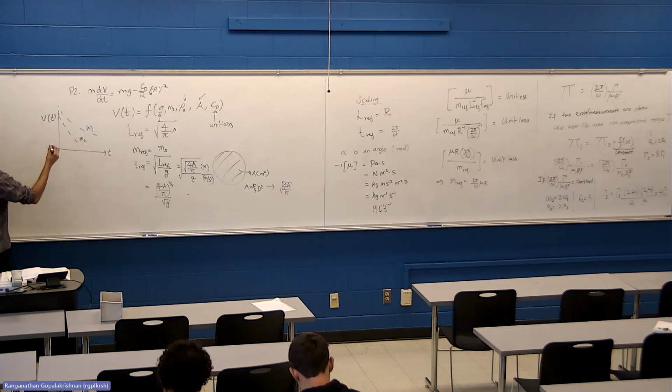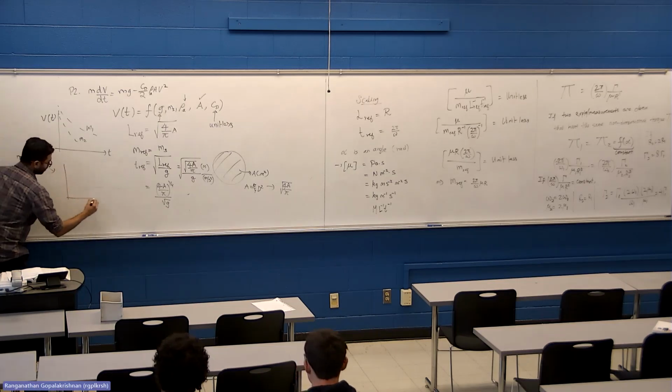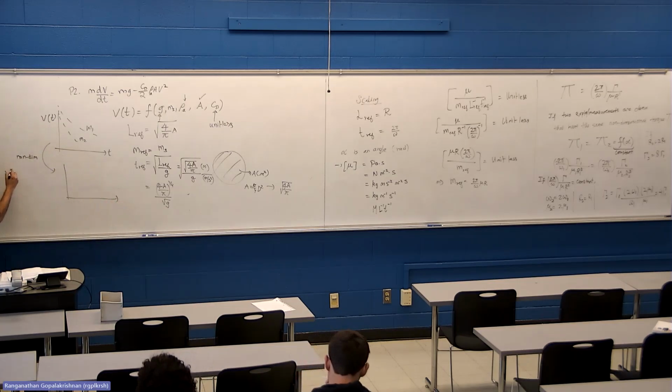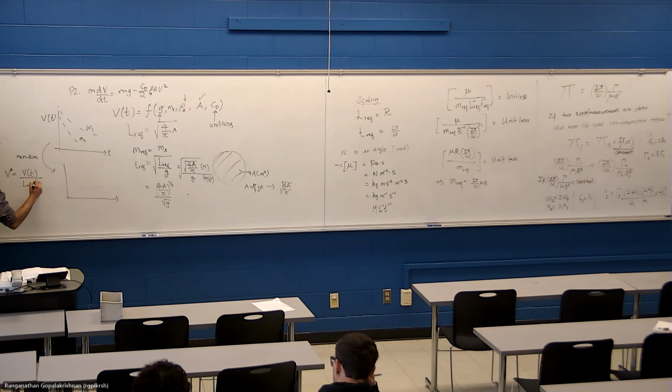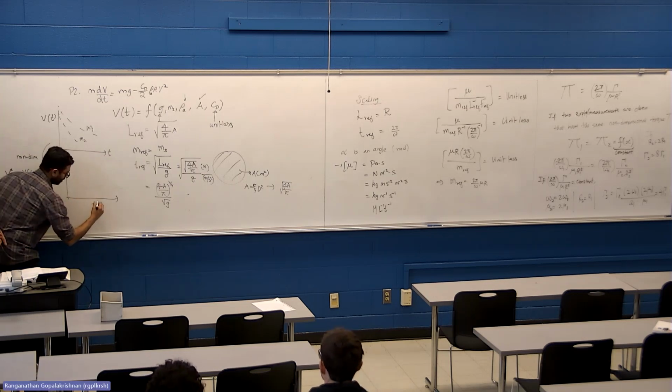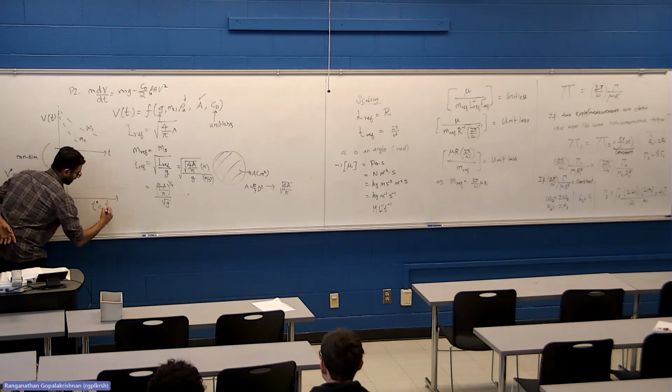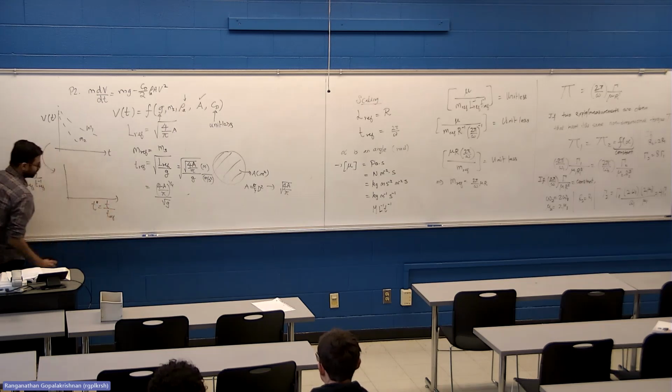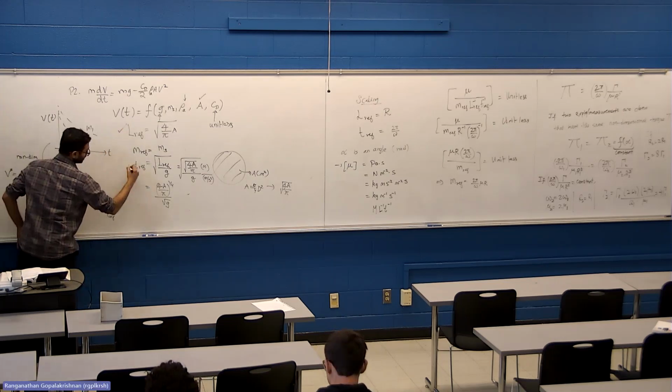So if the student or whoever is doing it wants to plot this in non-dimensional form, they would plot non-dimensional velocity, being the real velocity divided by L reference times T reference to the -1, and non-dimensional time would be time divided by T reference. So you have already identified what is L reference and what is T reference.